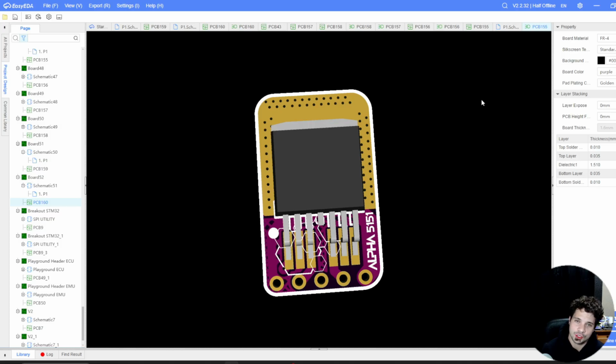Now, when we go back to the inside of the ECU, that IC14 module used for ECU VTEC conversion, when mimicking a P28 style ECU, it's the same thing. It's basically a miniature relay. And because of its micro size, there's a lot of heat generated. The original VTEC solenoid called for somewhere around 0.8 of an amp, so it was under 1 amp that it drew. But with people doing swaps, there's a lot of extra resistance introduced into the line from crimps and bad connections, old wiring, oil being put on the connection points, as well as the age of the components.